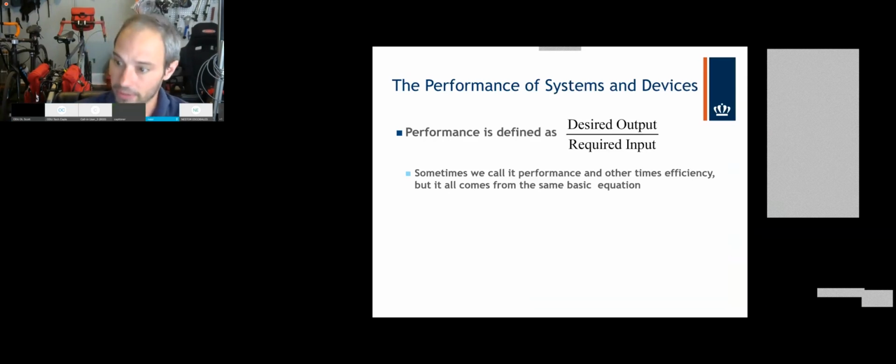In real life, it might be closer to 10, 12, 13%, but there's so much energy loss. But that's why we also have cogeneration power plants. Cogeneration says, all right, I can't convert all that thermal energy into mechanical work. The second law of thermodynamics has two statements. The Clausius statement says energy goes from hot to cold, and the Kelvin-Planck statement says that if you're going to try and produce power using a cycle by supplying heat energy, you can't convert it all to work. You've got to throw some of it out.